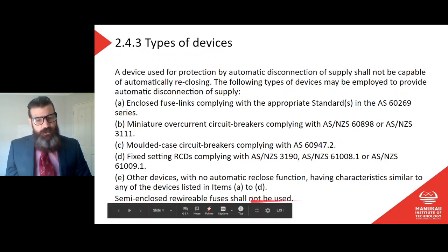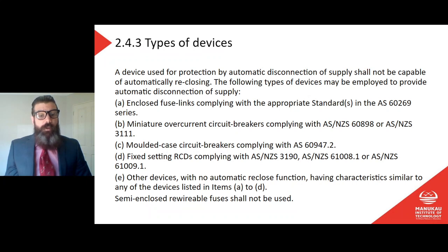Rewirable fuses are not used anymore. Doesn't mean they don't exist. They do exist. It does not mean that you cannot replace a fuse wire. You can, but you cannot install a new rewirable fuse. I would certainly recommend that if you ever come across a rewirable that needs to be replaced, as in the fuse is blown, you can buy plug-in circuit breakers.